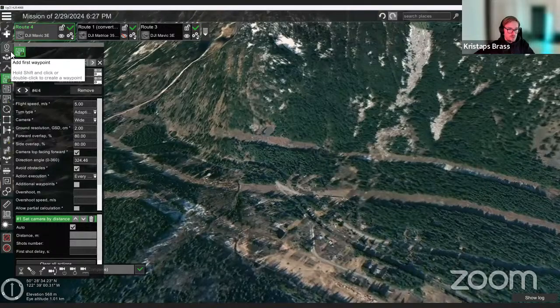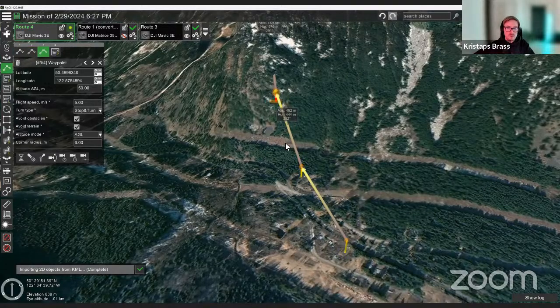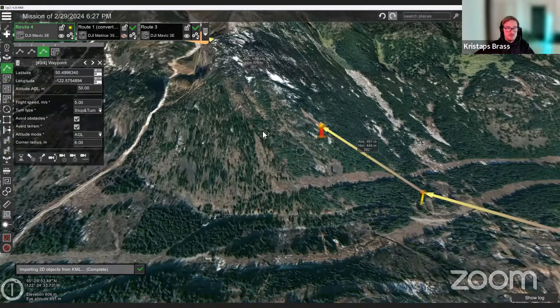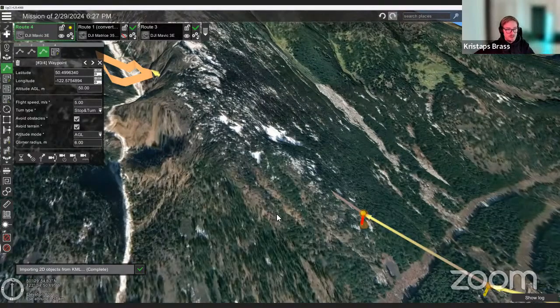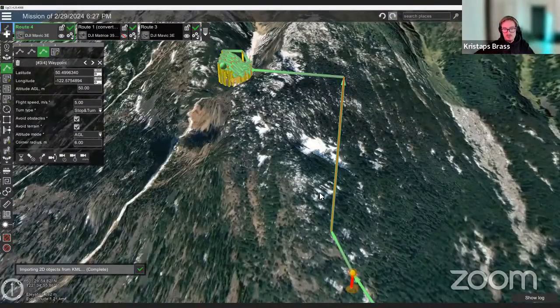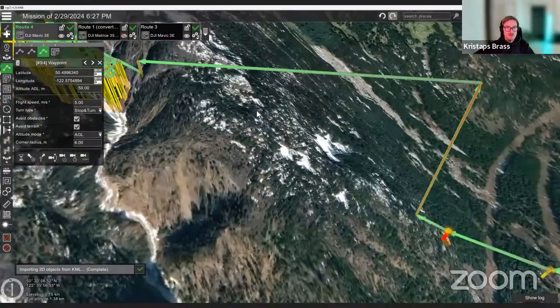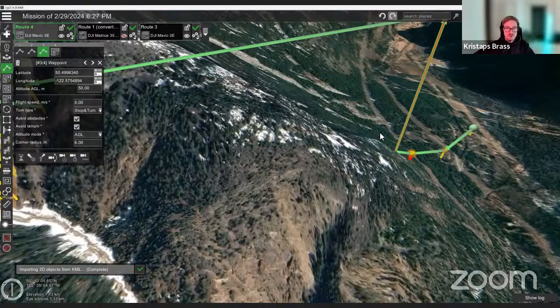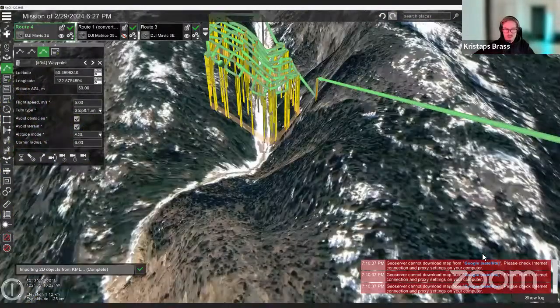I would not do this with normal waypoints because if you just put a waypoint here and then add a few more waypoints, the algorithm works in this case so that by design, it will not add additional waypoints between your waypoints. So in here, you can see, it sees that the flight has to cross this mountain, and here the minimum distance is 5 meters.